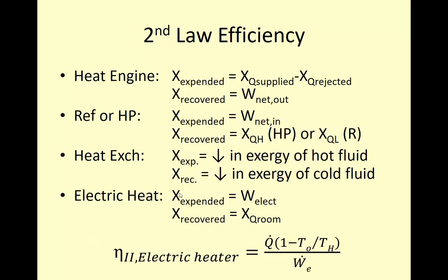So for a heat engine, the exergy expended is equal to the exergy of the heat supplied minus the exergy of the heat rejected, and then the exergy recovered is equal to the net work out. For a refrigerator or a heat pump, the exergy expended is equal to the net work in, and the exergy recovered is equal to the exergy of the heat source coming in to a heat pump, or the heat source at Q sub L for the refrigerator. And for a heat exchanger, the exergy expended is the decrease in the exergy of the hot fluid, and the exergy recovered is the decrease in the exergy of the cold fluid.